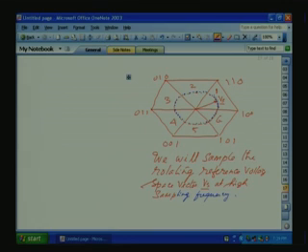Then this Vs we will generate by switching. Suppose Vs is in sector 1, we will switch between 1 0 0, 1 1 0 and the zero vectors 0 0 0, 1 1 1, such that the volt second balance is maintained, using volt second balance. See what is meant by volt second balance?